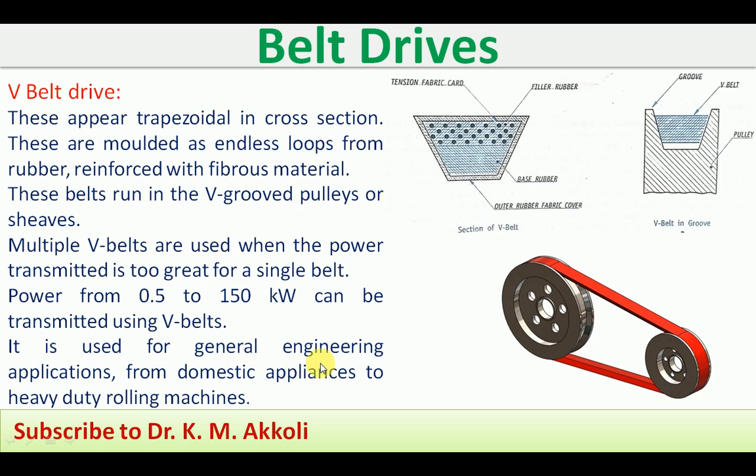It is used for general engineering applications, most of the machines, the machine tools. There the V belts are used, and for domestic applications and heavy duty rolling machines also we use them. Most of the machine tools use V belt drives, where the center distance is less compared to the flat belt drive.